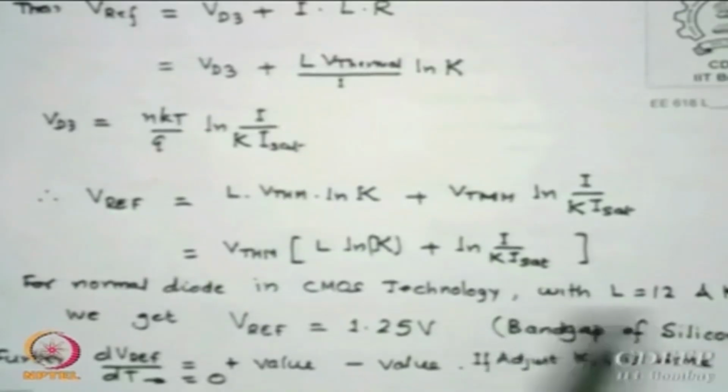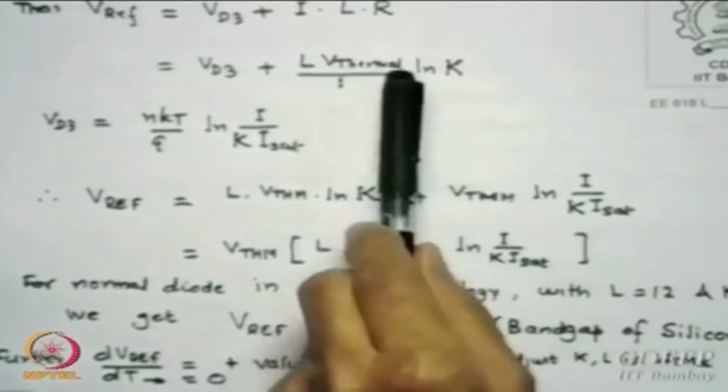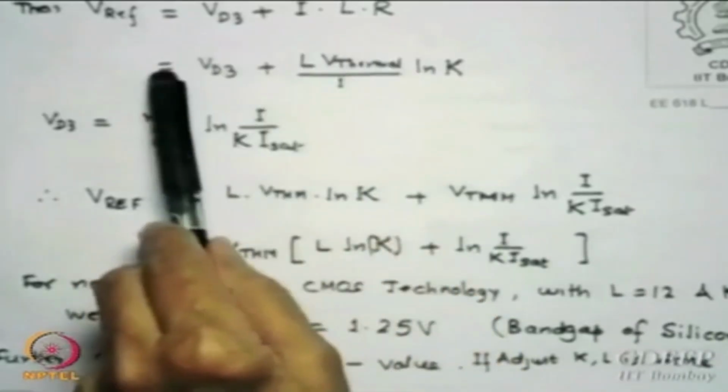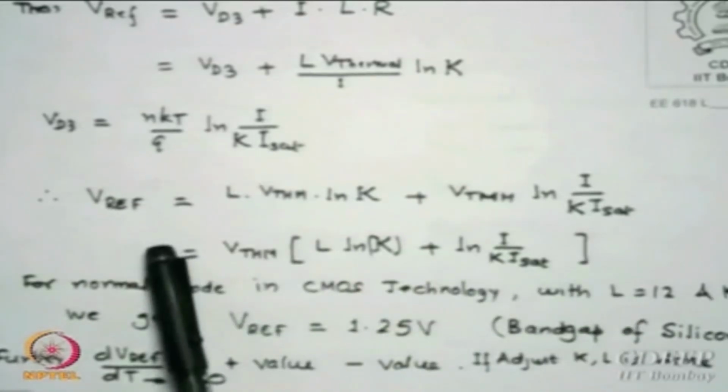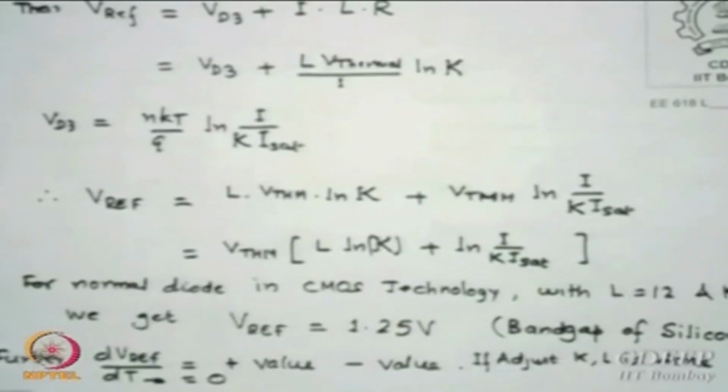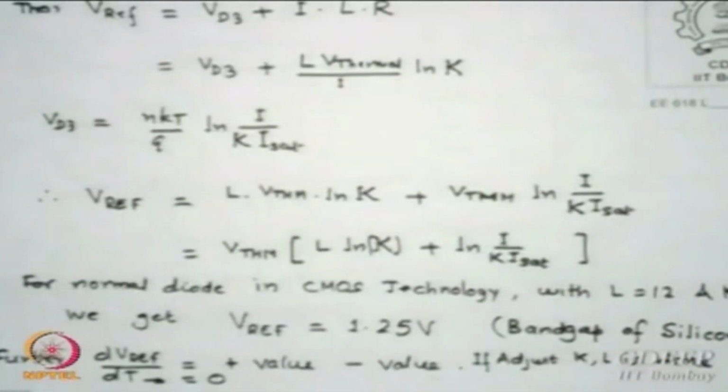And please remember, if I adjust these values, the TCF may not become 0 too much, because the same values will decide my reference. So please check how much accuracy you want for the reference voltage, it may be 1.2 or 1.25, anyway you need to have a fixed value. So you better try for TCF to be smaller as the first criterion of making this.